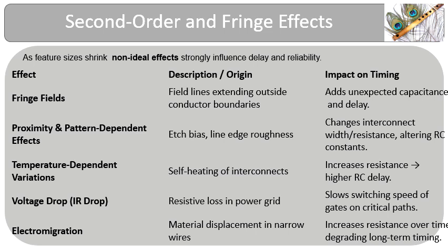Electromigration is a process in which atomic physical displacement takes place along the direction of current flow, leading to the creation of voids, the reduced net cross-section, and hillocks, the increased cross-section. Over a period of time, this leads to increased RC delay and risk of catastrophic failure. All such second-order phenomena put together impact the timing closure and signal integrity, performance and product reliability.